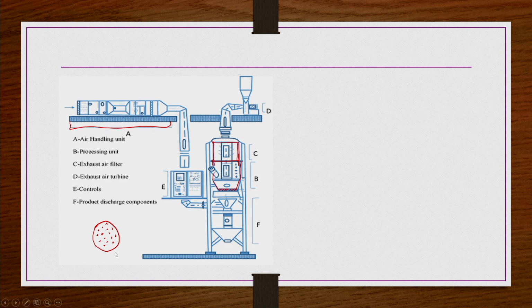So the air comes in here, something like this, and whatever particle bed is there here, it causes a lifting of the particles, because slowly when air comes in, at a certain stage the drag on the particle is balanced by the weight of the particle.